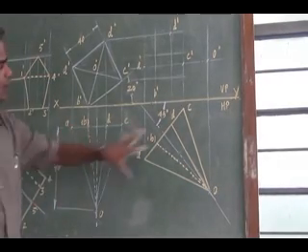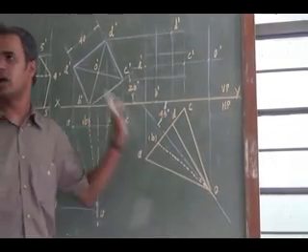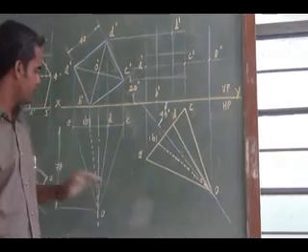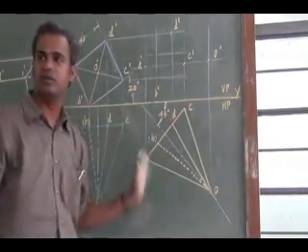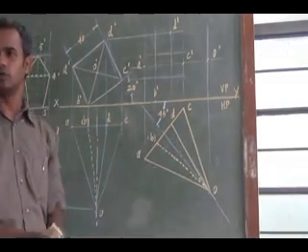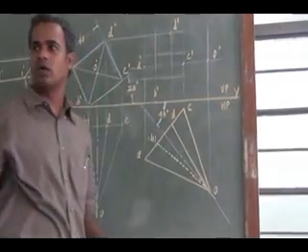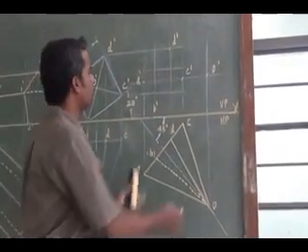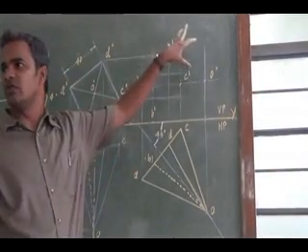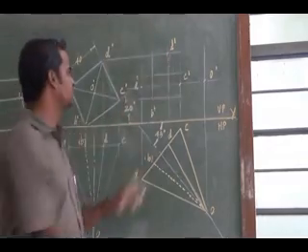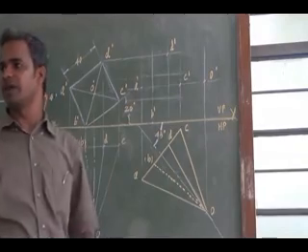Then I have to reproduce this in a 45-degree inclined manner. Just draw a 45-degree axis line, then reproduce the image and draw a perpendicular base to that. Then you reproduce the final top view. Then you project all the final top view points, the corners, to the front view. From the previous front view, you draw horizontal projectors. The intersection will give me the final front view points.